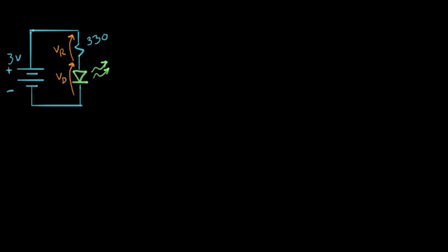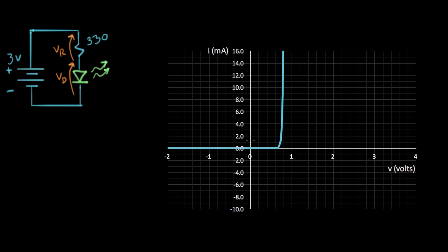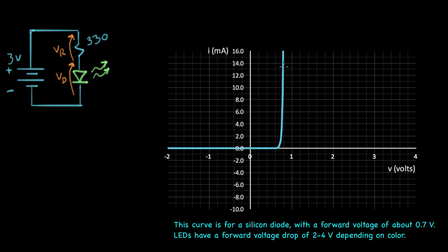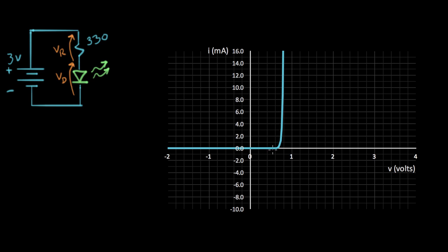So now I'm going to show you a plot of the IV curve of our diode. You can see right here around 0.7 volts, the current rises rapidly when there's 0.7 volts across the diode. Let's start with the same tools that we always have, which is let's try to write some current laws for these two things.